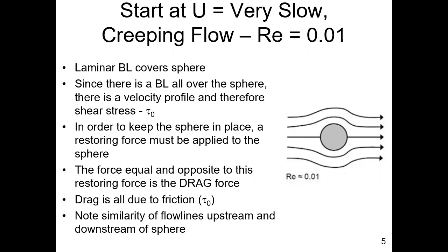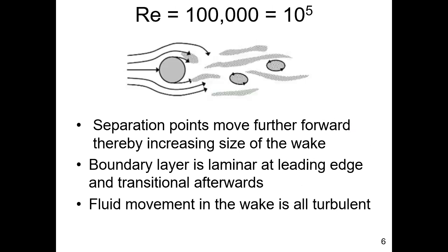At very low Reynolds numbers, when we were looking at flow past the sphere, we basically saw that we had all frictional resistance. But as we increase, say, the velocity and therefore the Reynolds number, ultimately what we saw was behind the sphere, there was a zone in which there may have been fluid, but it has no component of flux in the general direction of the free stream. That is, it was trapped in this zone, and that zone we call a wake.